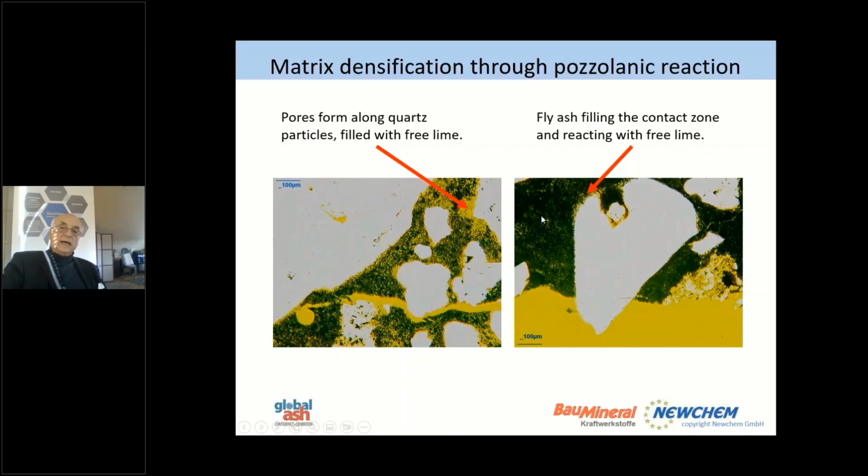It is a very dense mortar, and you can see that here on the rim we have a much smaller rim, and breaking the part away, you can see that we even succeeded in having a crack in the quartz particle. Therefore, you have a good glue for your aggregates, and that will strengthen your material and concrete.